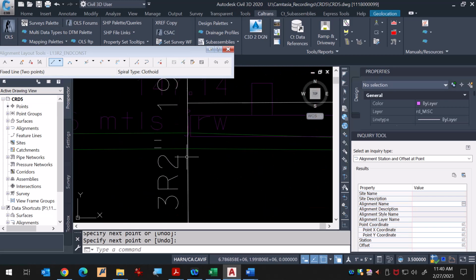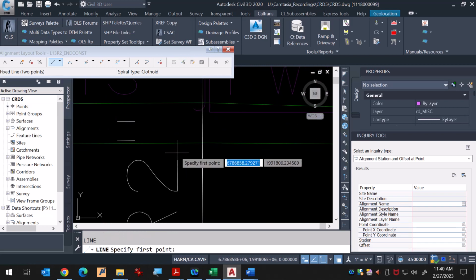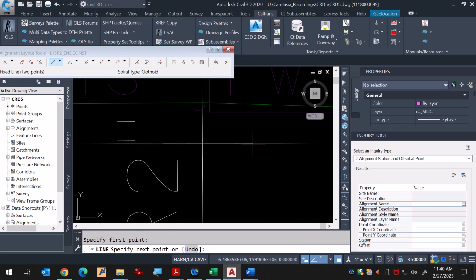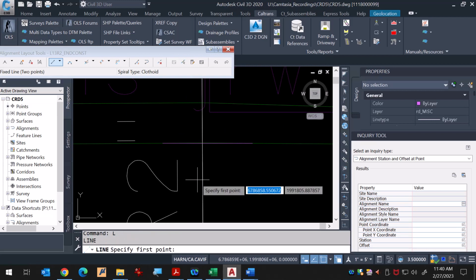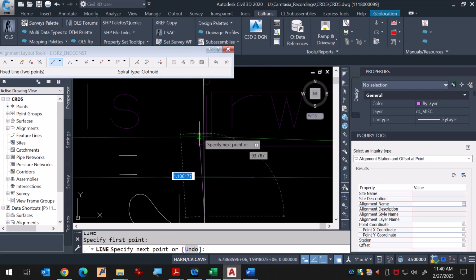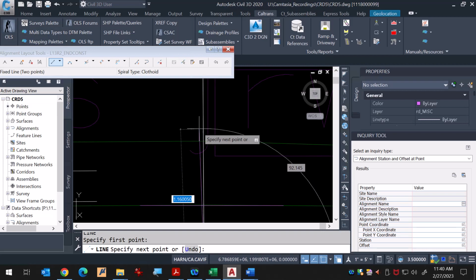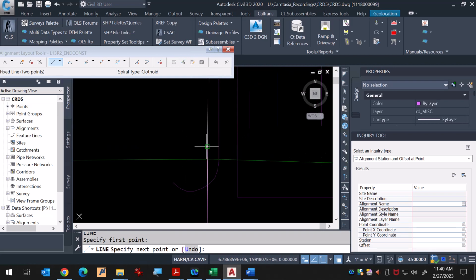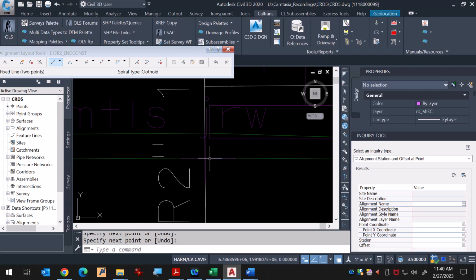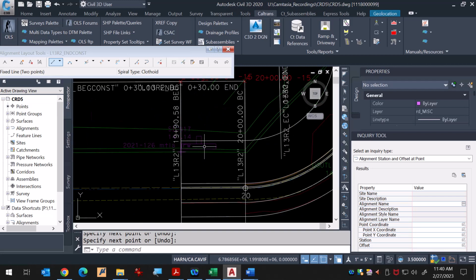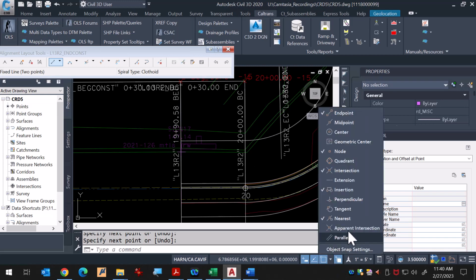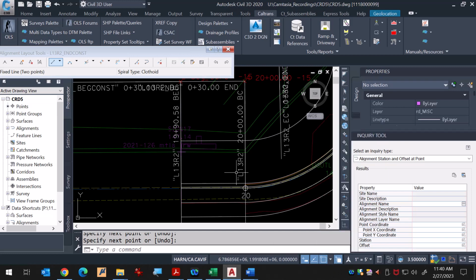And then we're going to do the same thing over here. We're going to do a line. So these are just temporary lines that enable us to snap to something that we know we're snapping to the actual, existing sidewalk. So there we go. We've got each side set up so that we've got that snap point. And let's turn the intersection snap on, and the intersection snap's already on. So let's collapse that. Now we're going to adjust the back of sidewalk.